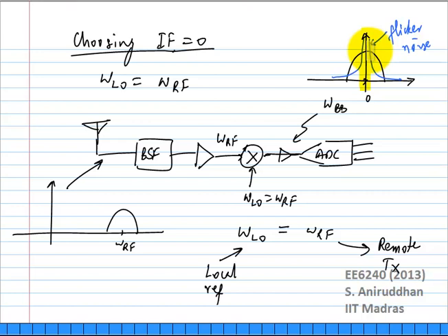So what do you do? One option is calibrate, right? Calibration is cancellation. I would assume one option is you measure the DC offset before you receive the signal and then cancel it out, and so you have a DC offset compensated amplifier. You can do it. Flicker noise will still be a problem. Maybe you can use very large devices, burn a lot of power.